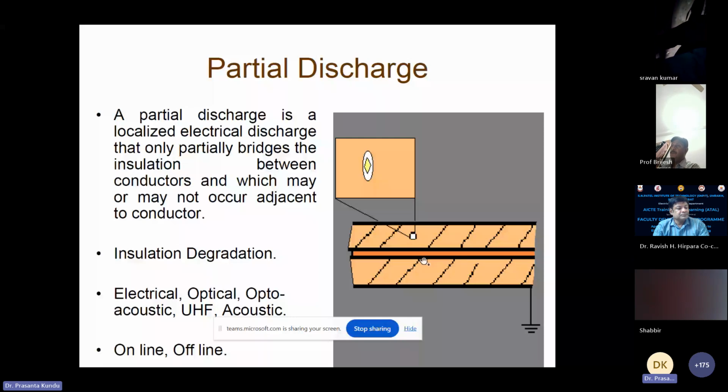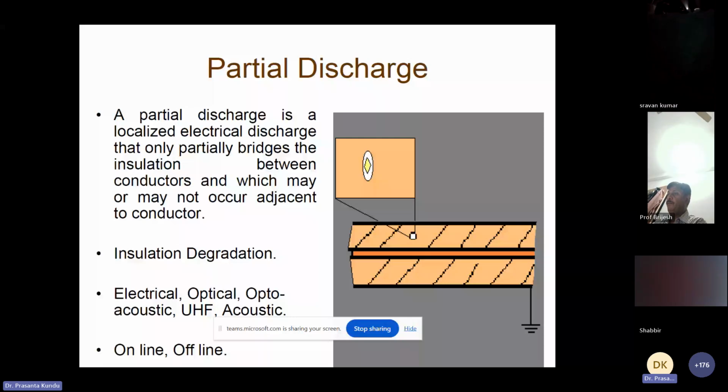That is happening in any electrical apparatus, any power apparatus, including transformers, rotating machines, cables, capacitors, whatever we can have. There will be a high voltage part, and the ground or low voltage part, and in between there will be insulation. Now, if the insulation is composite, having different insulating materials like solid, gaseous, or liquid insulating material, they have different permittivity.